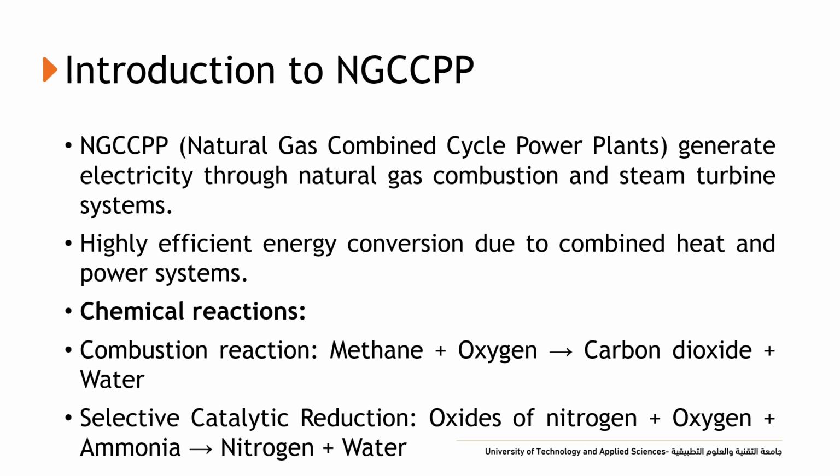And in controlling the emissions, there are two reactions taking place. One is the oxidative catalytic reaction, in which incomplete combustion products such as carbon monoxide react with oxygen to produce the complete combustion product carbon dioxide. The other is the selective catalytic reaction, in which nitrogen oxides react with oxygen and liquid ammonia to produce nitrogen and water.